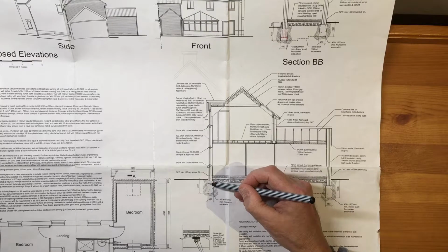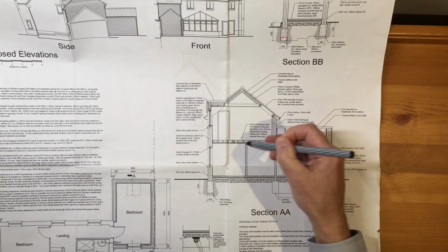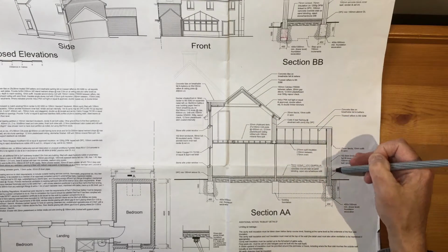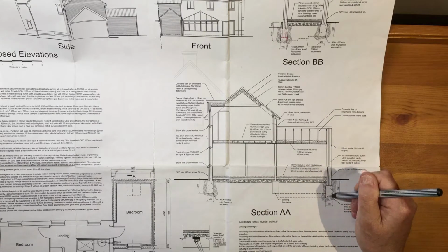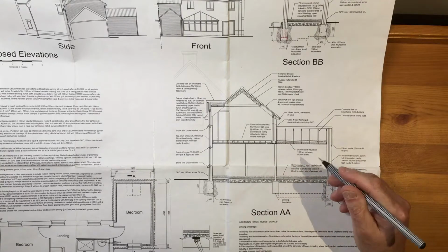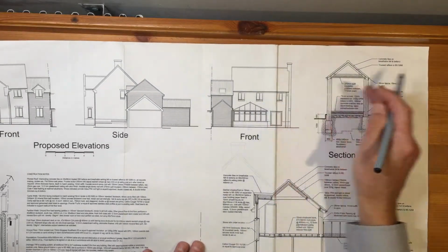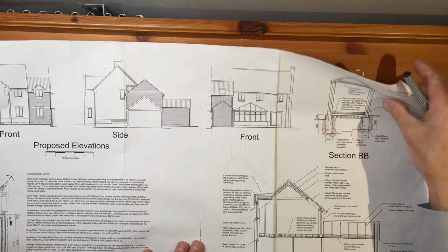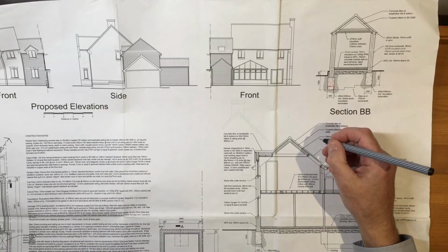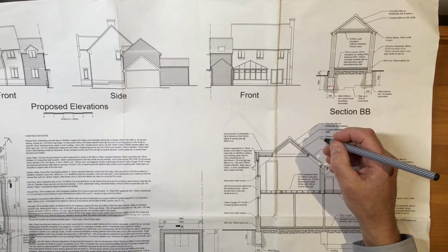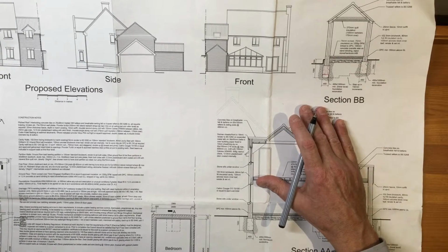And you've also got to calculate all the materials in making the structure and have the materials ready on site as and when the parts of the project have been constructed. So you would have to study all the elevations, scale them up and work out the quantities of all the materials. And that's what a quantity surveyor does. Works out the quantities and the prices.